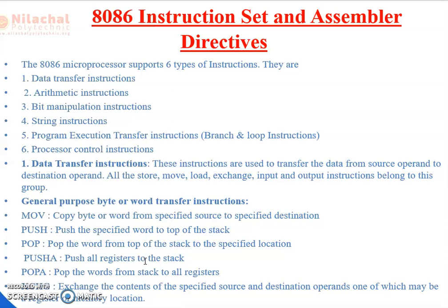Then PUSHA. Push all registers to stack. POPA means pop the word from stack to all registers. Then XCHG means exchange the contents of the specified source and destination operand, one of which may be a register or memory location.